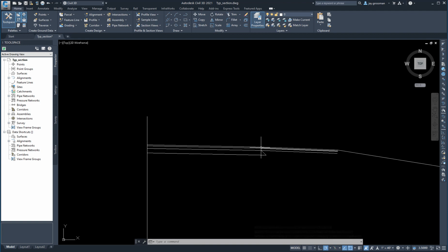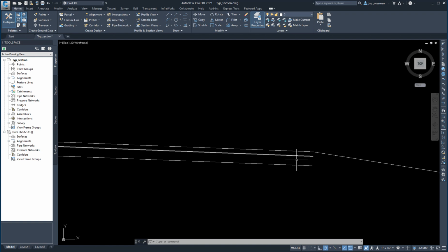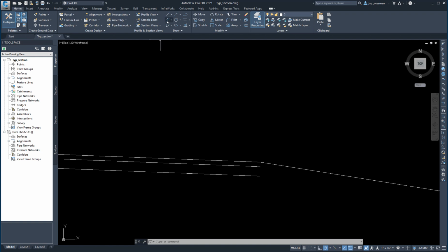You can show this as a vertical. We used to draw them that way as a vertical line, and then we're like, well, usually they spill out a little bit in construction, and we don't want a vertical line on the edge for safety. We really want the contractor to swing them out a little bit, so we show them more at a 45-degree angle now. You can still show them vertical. In this case, it's just a typical for there.